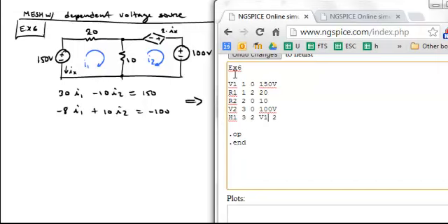So if you did not have a voltage source in a branch, and it was that branch current that you wanted to use as your controlling current, what you'd have to do is actually add in a voltage source in series, say with a resistor, if that was the current you're trying to pick off.